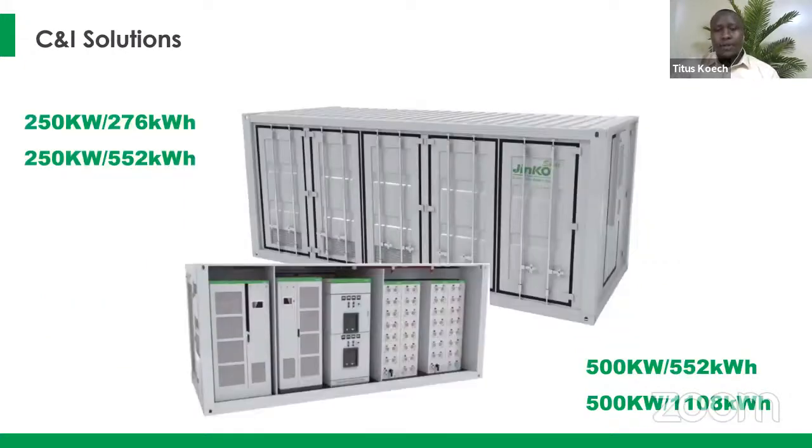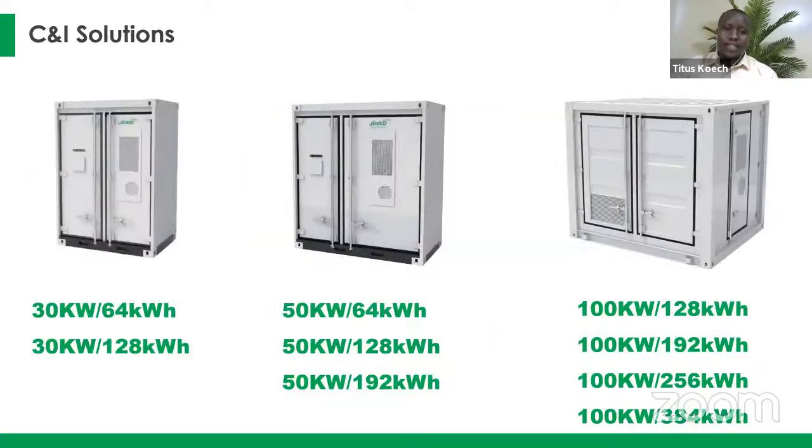And also, these are for the bigger solutions. There is from 250 kilowatt for the PCS and 276 kilowatt hours for the batteries, all the way to 500 kilowatt for the PCS and 1108 kilowatt hours. And one thing about all these solutions that we are offering is that you can easily have the units in parallel. Like now for these particular units, you can have up to 3 units connected in parallel, to be able to expand your solution.